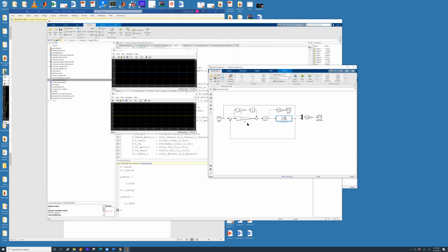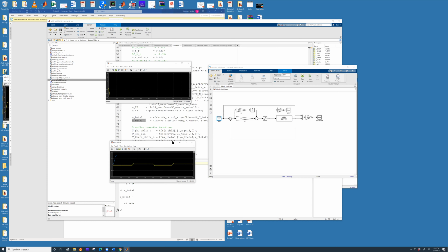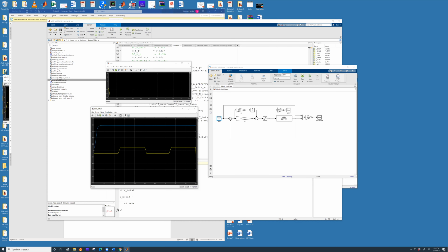Okay, everyone got this? If you just want to see how well this is working, you can actually give some non-zero side slip, say 10 degrees, and run and see how it is working. Now you would observe that unfortunately, for a non-zero side slip, the system is not working out, which means the gains are not right. So you want to tune the gains.